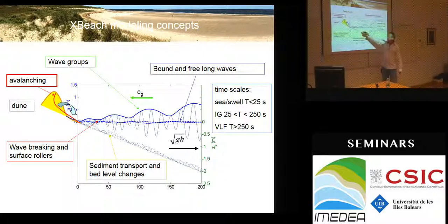And then we couple all of this to sediment transport. Typically where the waves are high, you have a lot of sediment in motion, and that's then transported by the waves themselves, but also by the mean currents and the infragravity waves. And then XBeach, which is the model that we're using, also has a module in it that accounts for avalanching. If you have a storm, there's a surge level, so the wind pushes up the water. These infragravity waves run up the beach, and then the sand actually slides down in an avalanching motion.